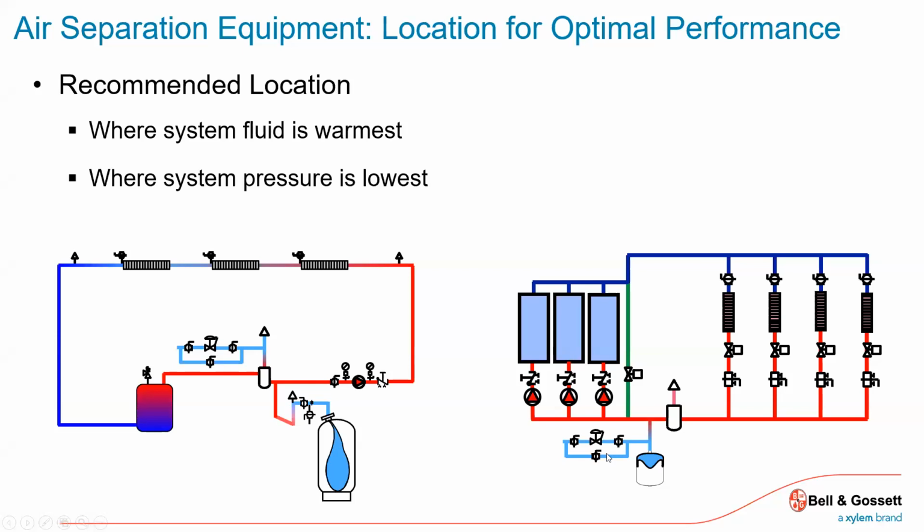Typically, when the chiller is working, I'm actually lowering the water temperature, right? So where is the most expansion? Where's the water the warmest in a chilled water system? Yeah, it's on the return. And then if the chillers for some reason were off and the water experienced ambient temperature, it could be as warm as 80, 85, 90 degrees.